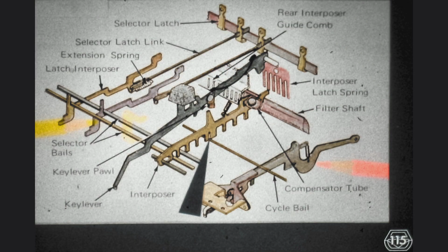If you said loosen the front one first, you are on track. Loosen the nut on the front screw, make sure that screw itself stays tight, and then you can safely loosen the rear nut and screw without losing the cycle bail up-stop position. That frees the character interrupter support bracket to move front to rear.